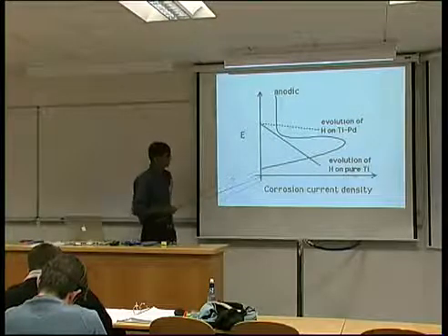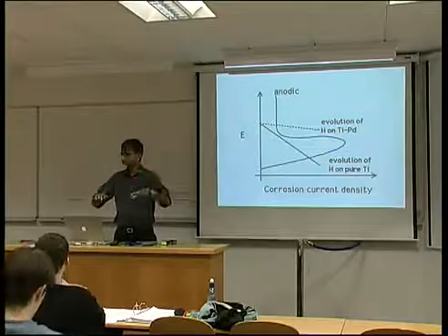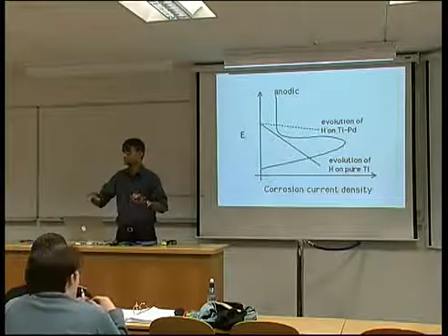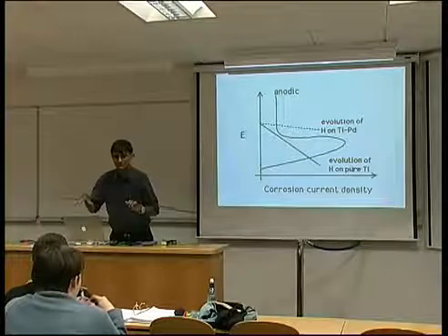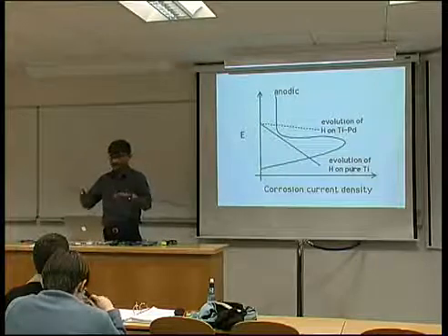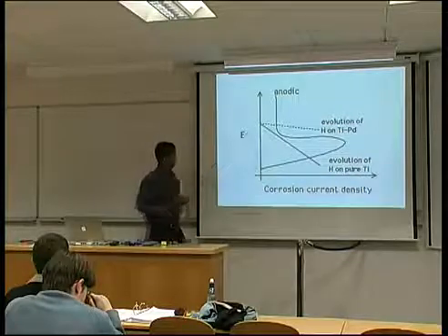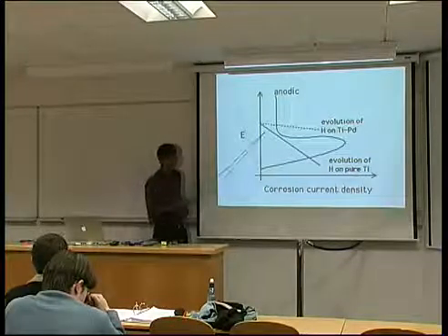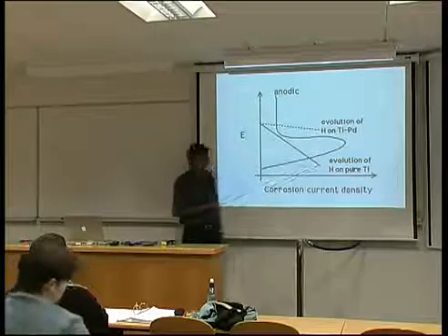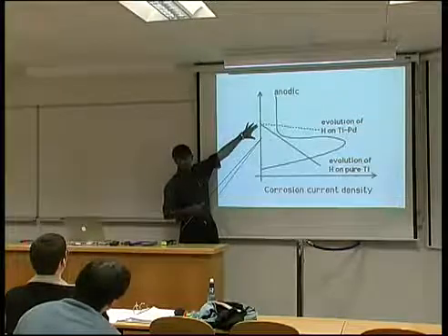So supposing I take a titanium, then for corrosion to happen, you have to have an anodic site where the metal is dissolving, and a cathodic site where you might have hydrogen evolution or oxygen reaction going on. Does this ring a bell? So you need two. You need anodic and cathodic sites. At the cathodic site, if you're putting titanium in acid, then we will get the evolution of hydrogen. So this is the rate at which hydrogen evolves as I alter my electrochemical potential.